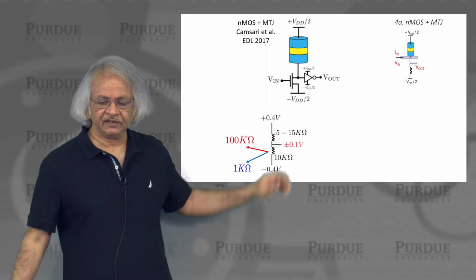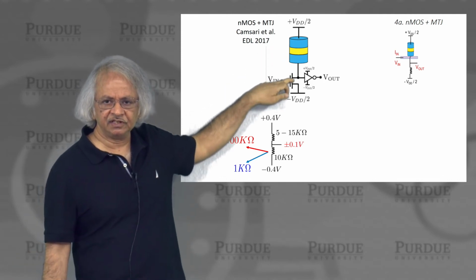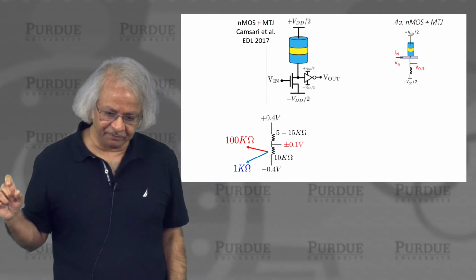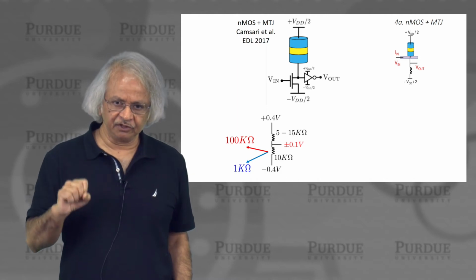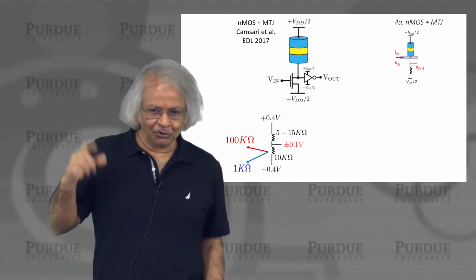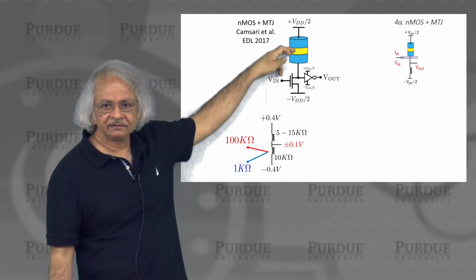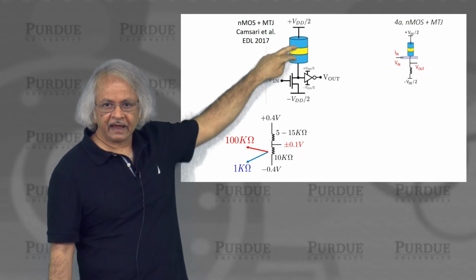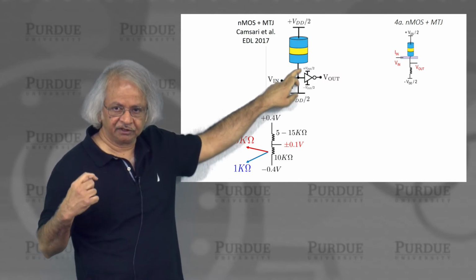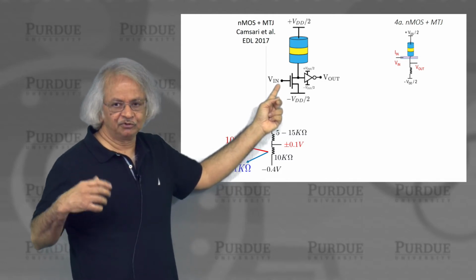Next. So here the idea is that you just take a regular MTJ, the ones that, as I said, are the basis of this embedded MRAM technology, in series with a transistor. The only difference being, of course, in the actual technology that people are developing, they want stable MTJs because they are trying to store information 0 and 1. But of course, one of the problems, as I mentioned, is you get a lot of bad magnets, junk magnets, which you have to throw away. And those are the ones that I am arguing could be useful for what we are talking about to implement p-bits. So what we want is these unstable magnets whose resistance fluctuates here, and as a result the resistance here also fluctuates, and what we are looking for is a way to control that fluctuation with a third terminal. And the point, and that's what was shown in this paper, is that this gate voltage of the transistor could help you do just that.